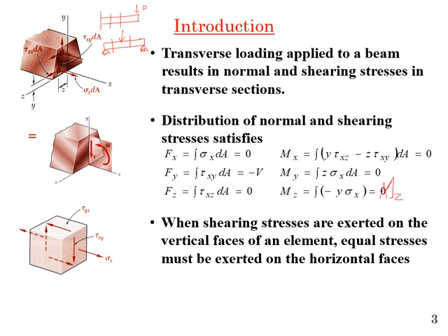And this will change into the flexure formula, Mz, not equal to 0. And we know that the cross moment of area was equal to 0, and there is no moment about the x-axis, so that's why these terms will be 0.